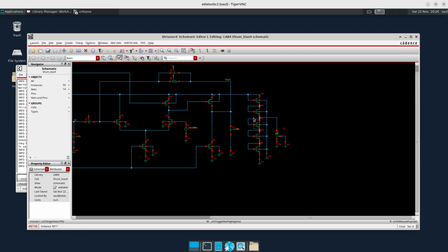So I can tap in the one voltage that is closer to the voltage that I want, and I also have a large capacitance that is shunting that node to ground. That is important because there will also be noise coming, and we need to filter that noise to ground, and we need to reduce the impedance also. Remember that the voltage reference, the voltage source, has to be low impedance, so I reduce the impedance by placing a capacitor to ground. Okay, so there are implications of using this structure.